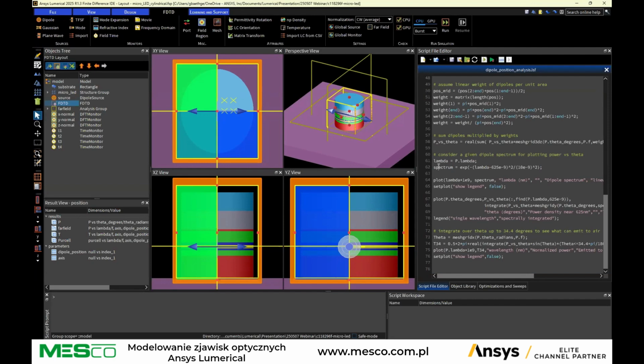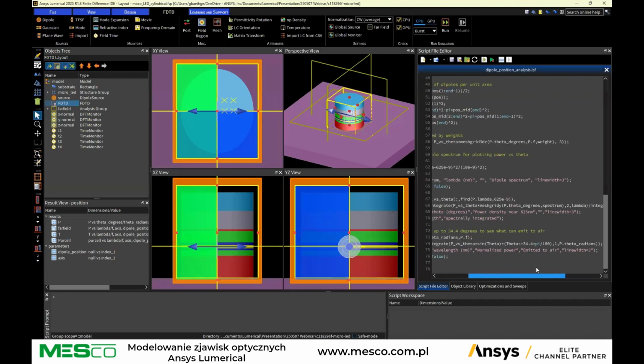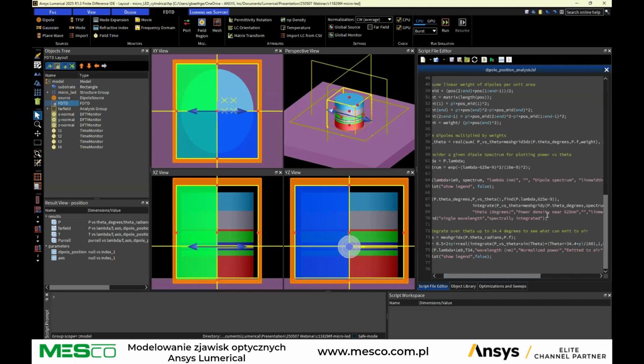Here, instead of using a Gaussian spectrum, we could use the results from the MQW simulation, for instance, and we do the integration over the wavelength. It's normalized to the integration of the wavelength. Here, basically, we define that spectrum to be centered around 625 nanometers, and so we do this power density around that wavelength, and so that's what we do here.